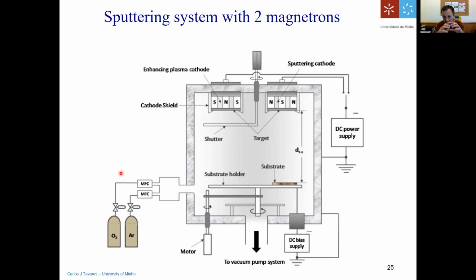That's why they are so expensive. This can be done by sputtering, or by thermal evaporation, and you have to do 90 different layers. You stack these layers, and these layers can comprise zinc oxide, silicon oxide, titanium dioxide, because you're just playing with the optical properties of these layers, the thickness, and their electric properties and refractive index properties. So you can fine tune to enhance this transmission of light, which is really crucial for the best cameras for professional photography.